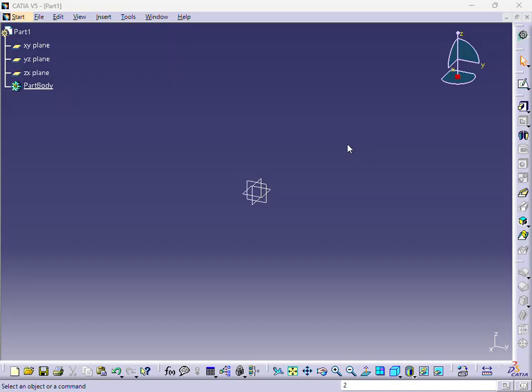So, what we have here is a simple brand new part. We've got the three default datum planes, and in the upper right hand corner we have the regular sketch, referred to as a standard sketch, or sometimes referred to as a sliding sketch. All that means is the system's going to default a lot of the values for you. And we also have, if you hit the drop down arrow, what's called a position sketch. The position sketch looks like it has a dialog box in front of it. Now, the difference between the two is one defaults all the settings and the other one gives you control of those same settings. A lot of times standard sketch works just fine.